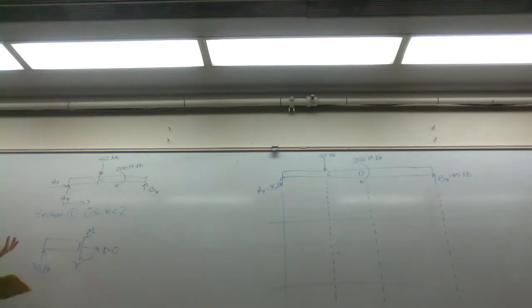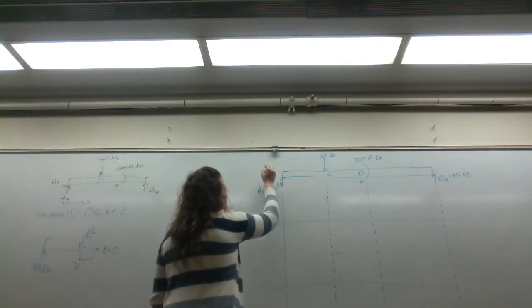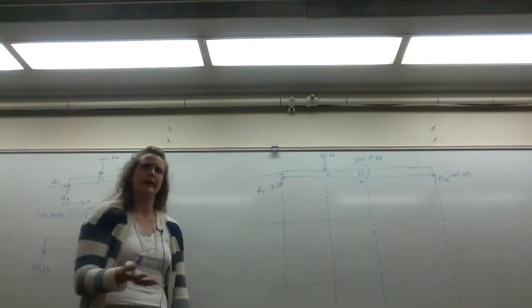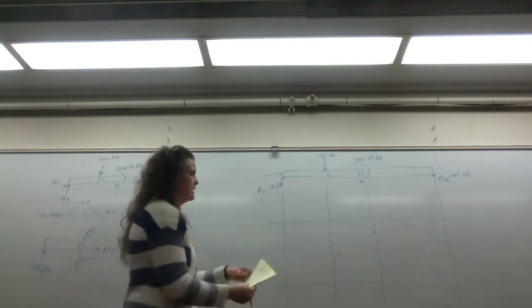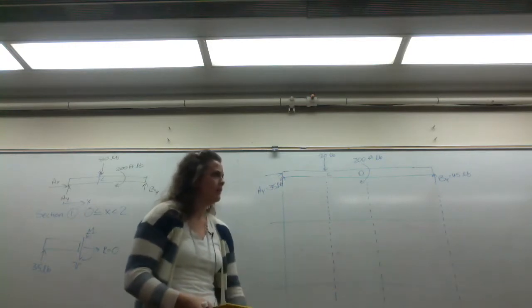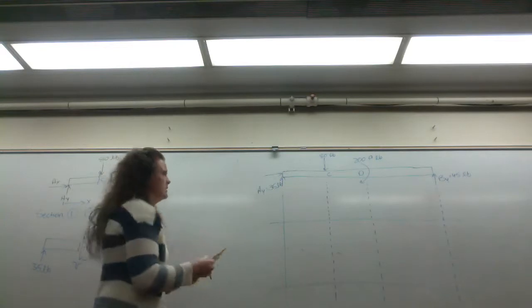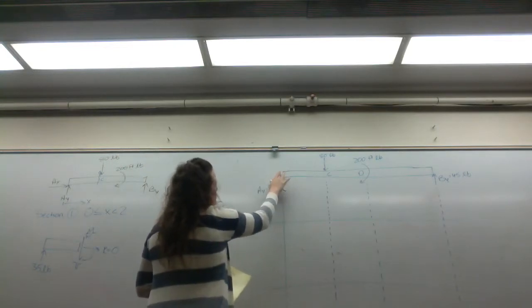We really, in the next 2 lectures, and in your 5th lab, we're only going to focus on shear and bending. That's the interesting stuff. Your axial force is only going to change, okay, if you have some loading conditions that are applied laterally. And those will remain constant throughout the beam. Unless there's some sort of internal gear or something that's applying loading conditions within the beam.